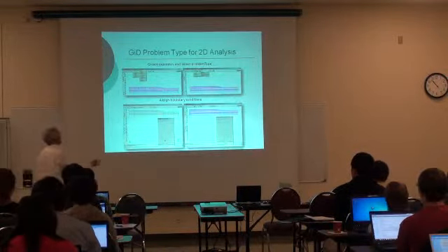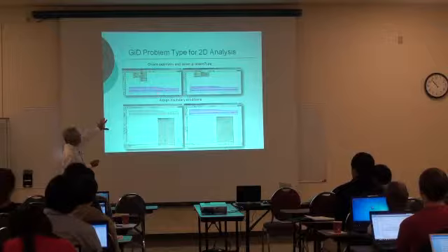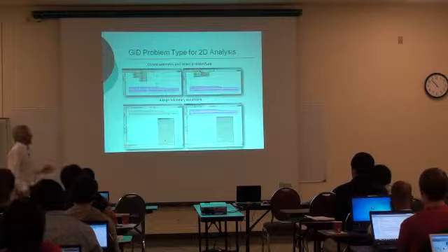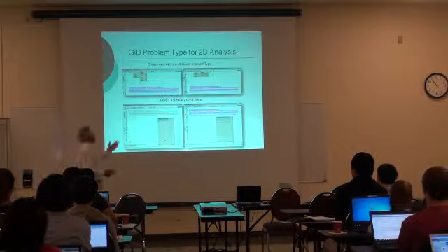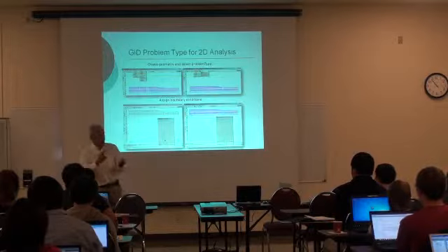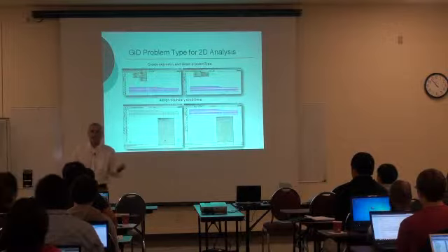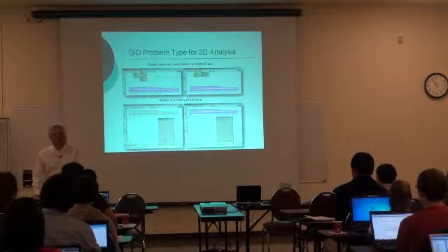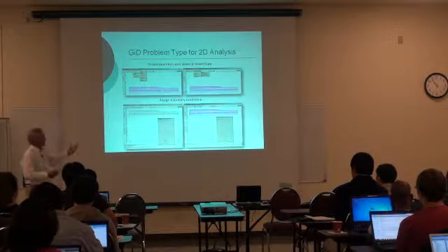A problem type that is done in GiD, that takes the information, the CAD information or the element information, and outputs a file that can be customized as you want. So what we have done is to customize it so that it's for OpenSees. Now, we haven't included everything. What I have included is just the things that I want to use: solid elements, PY elements, contact elements. You're not going to find all the other commands that are available in OpenSees. That would require a huge effort to develop a problem type that is complete enough for that.